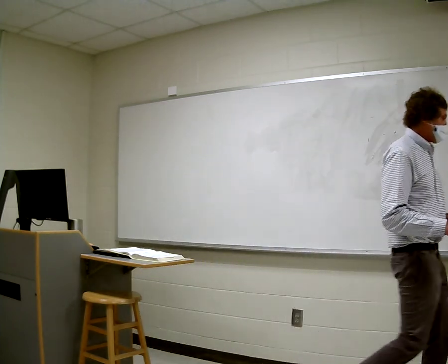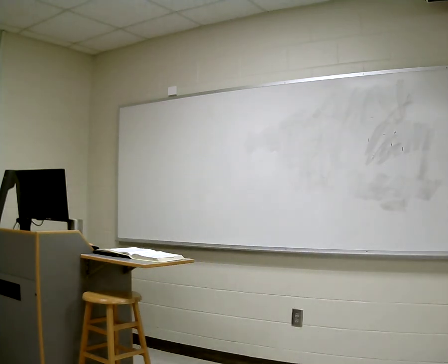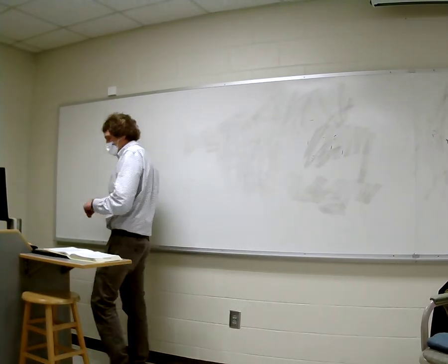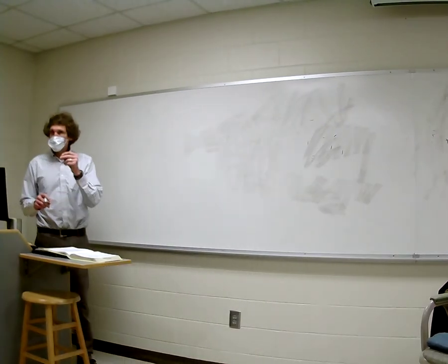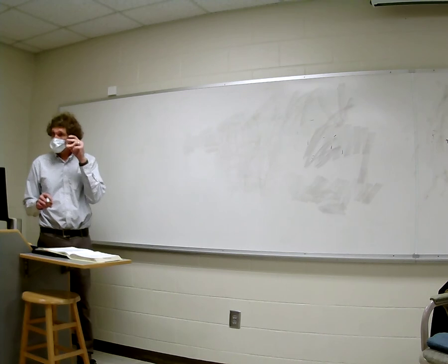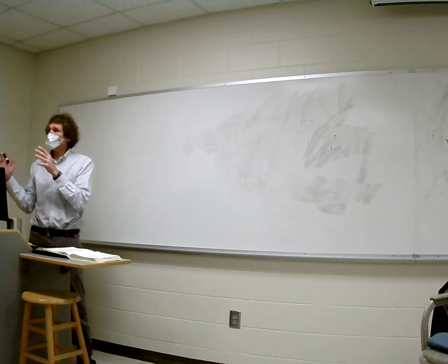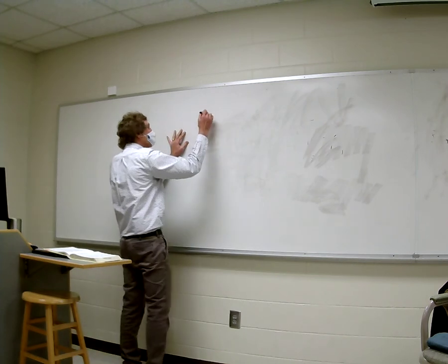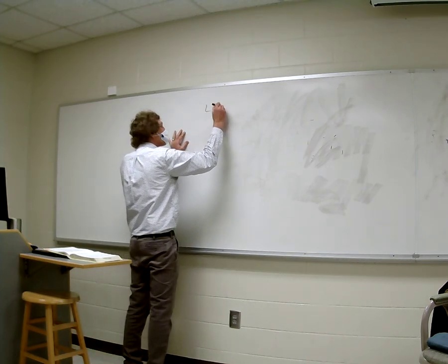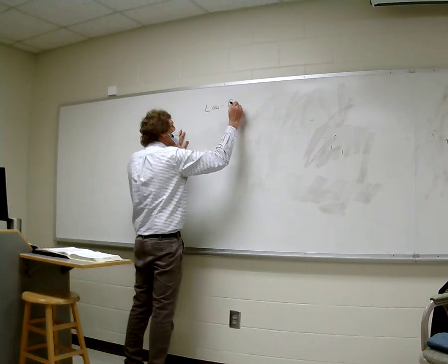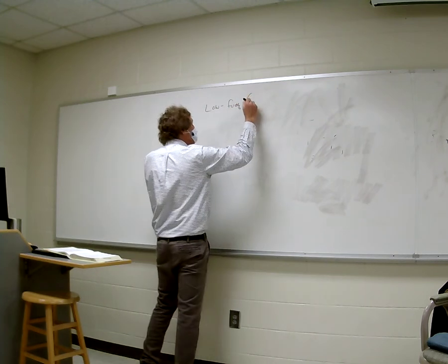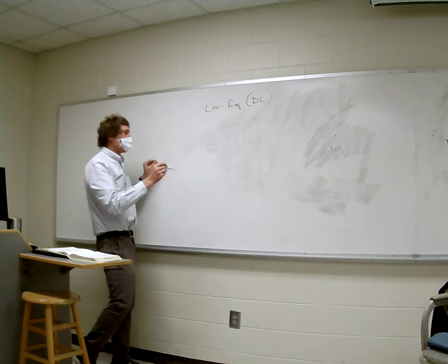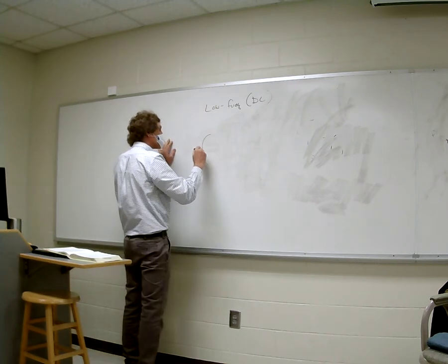We're going to start with a wire. We'll go for wire, the inductance and resistance of the wire, both AC and DC. Then what I'm going to do is resistors, capacitors, and inductors. I'm going to show you the equivalent model at different frequencies. So first put down low frequency. You can put down DC too. By low frequency models, if you have a wire, write this down.